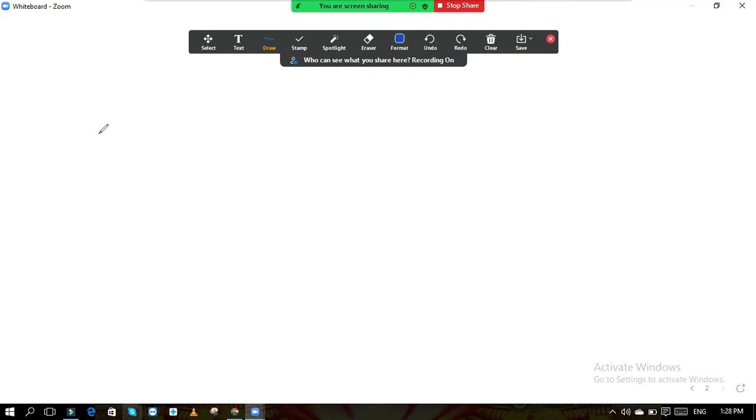The one center point that you get for all the loads, that is your loading centroid, and geometrical centroid, you know that. Okay, we have already studied in detail. So in the stability calculation we are going to see whether our force or loading centroid and our geometrical centroid are coinciding, lying on the same point, or there is some eccentricity between those two. And if the eccentricity is there, then we have to consider direct stresses as well as bending stresses. P by A plus M by Z. That is the basic formula.